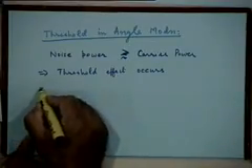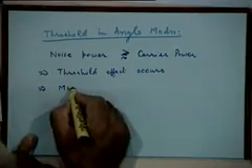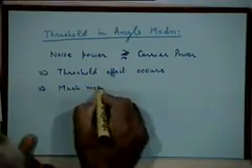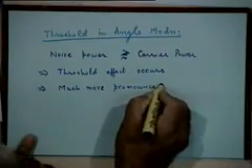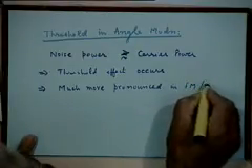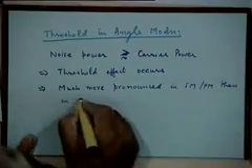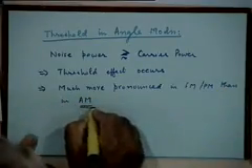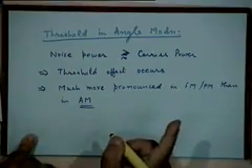So the second important point I want to make in this connection, which I already said, is that this threshold effect is much more pronounced in FM or PM than in AM. And remember, in AM it does not occur always. It occurs only when you do envelope detection.